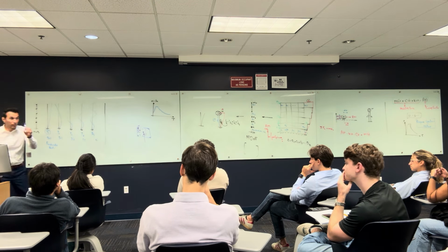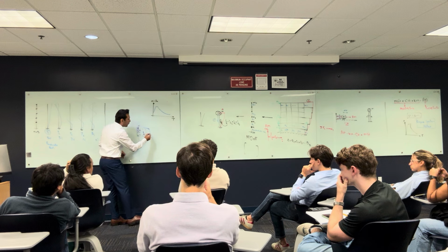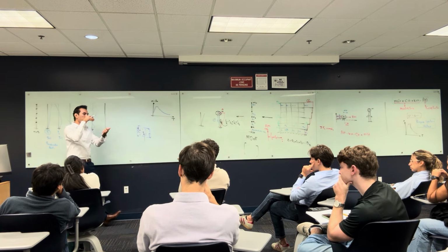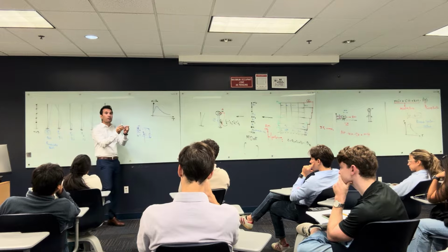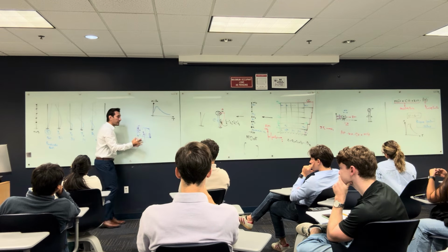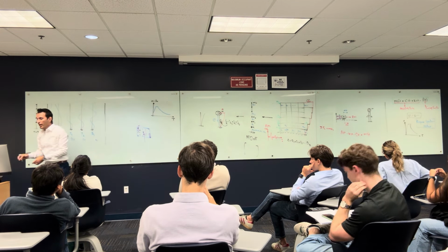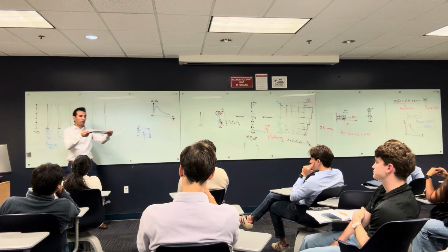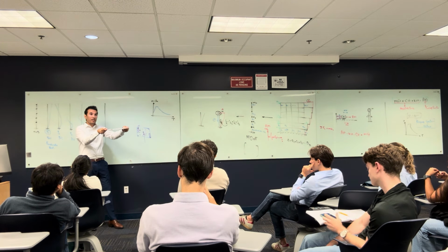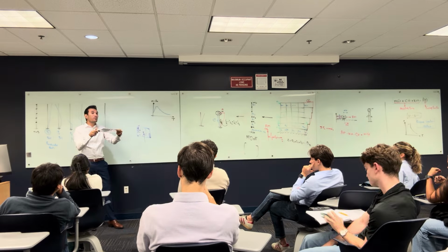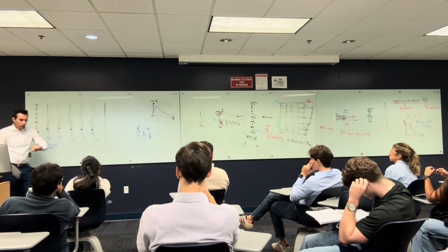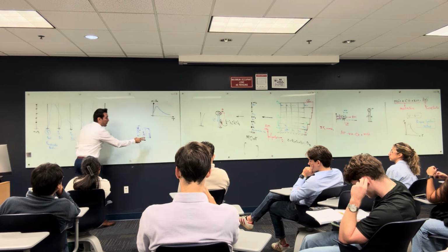So if you wanna make this system much better, I would put a shear wall here to bring the center of mass and the center of rigidity closer, not to put them on top of each other, but at least make them close to each other. Okay? So this is gonna be a much better system. Rather than this one moving that way, I have another system, so rather than making like this, we can make like this. Because torsion makes a lot of shear on the columns and the shear wall. You don't want that, okay? So that is for this one.